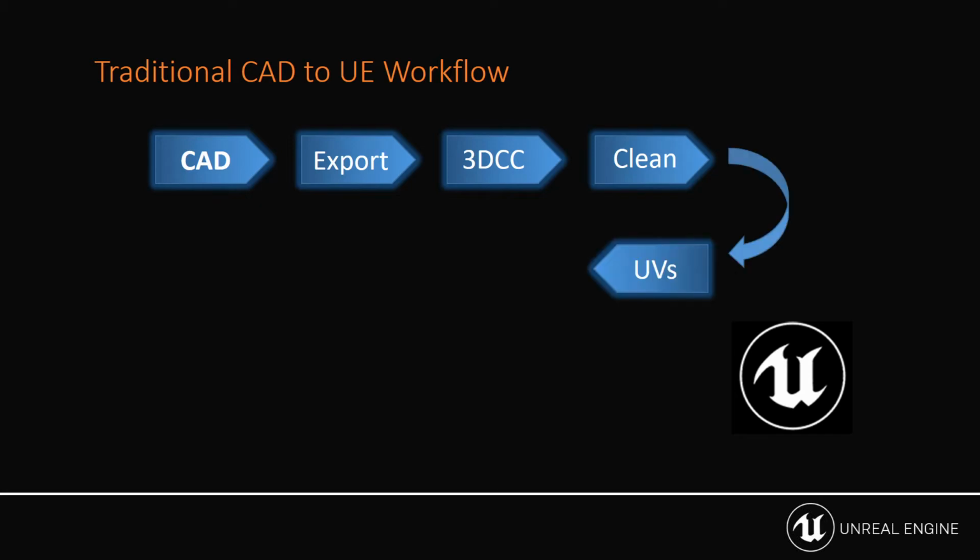And of course, we need to think of things like UV layout, that is for texture coordinates. But we need UVs for more than just texture coordinates. We need them also for light maps and things like that as well, for baking lights within a real-time environment like Unreal Engine. So then we get into organizing the scene. Perhaps we've lost hierarchies or any of our scene assemblies that we need to rebuild. Now we may need to convert the data.